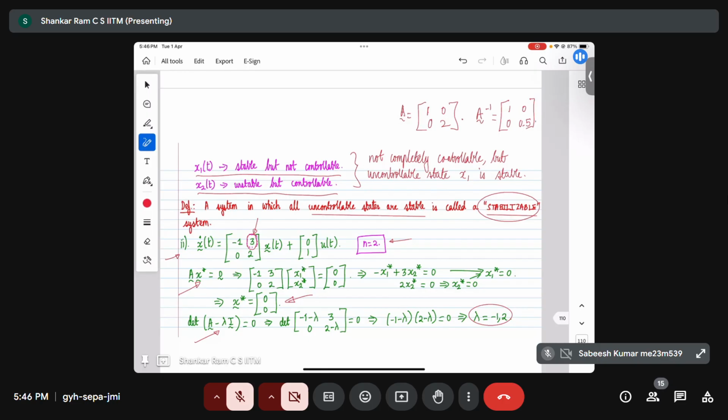See, the definition of stability is what it is. You perturb a system, and whether it comes back to the equilibrium state is the same for non-linear and linear systems. But for LTI systems, we converted the definition to a criteria on the eigenvalues of the state matrices. Similarly, the notion of controllability is what it is. We wrote down a nice criteria for LTI systems. Things become complex if you go to non-linear systems. Maybe it might be more than these eigenvalues, something other might also come, because you don't have a state matrix and all in a non-linear system. Okay. Thank you.